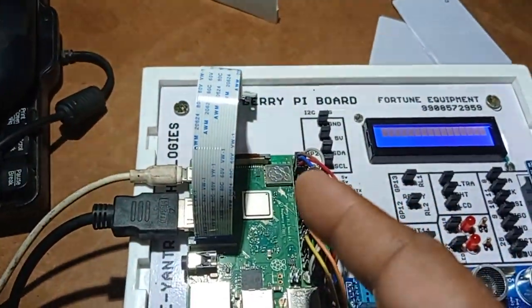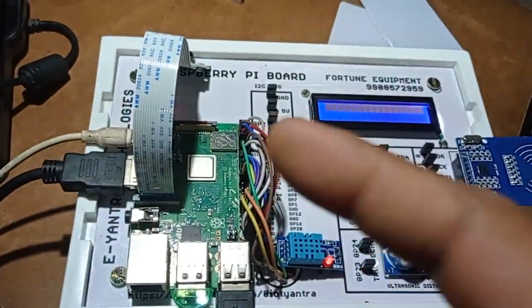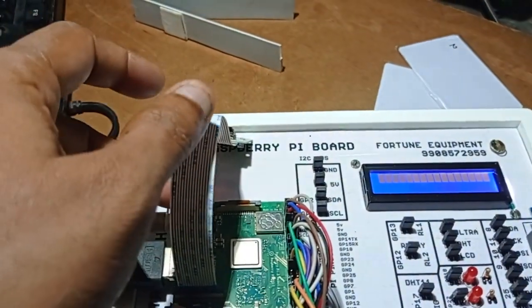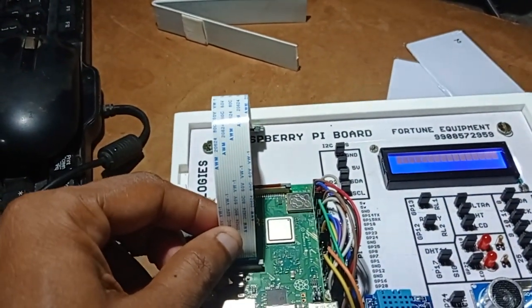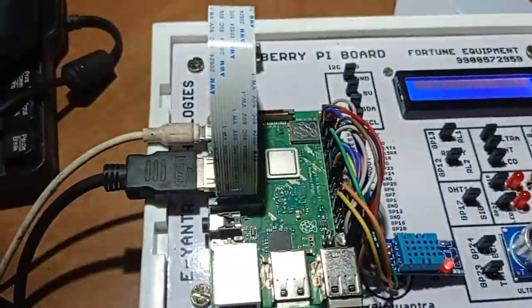In this present video, we are going to learn how to make image capture using the Raspberry Pi camera, and then we are going to see how we can apply various filters to the obtained image. There is no need of any connections except this Pi camera. We'll just insert the ribbon cable of this Raspberry Pi camera into this camera slot, and then just push it.